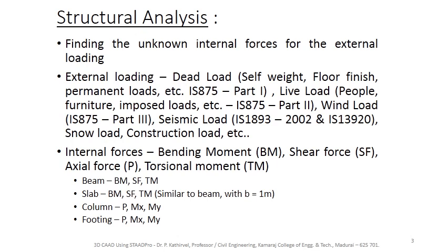And then there is possibility of wind load as per IS 875 Part 3, seismic load as per IS 1893 2002, and IS 13920, the ductile detailing code. In addition, the various other loads include the snow load, construction loads, etc. So due to the external loads applied on the structure, internal forces get developed in the structure. Finding out these forces is known as structural analysis.